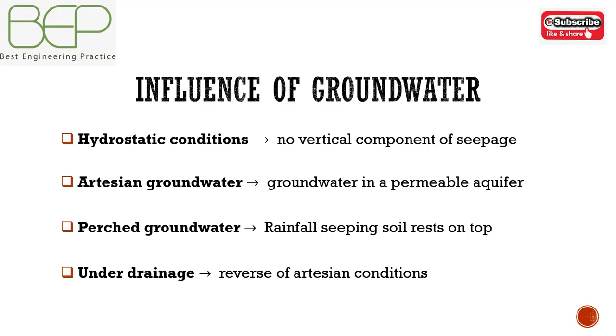The form of groundwater is important not only for the design of the permanent works, it has very serious implications for construction costs because of its influence on the difficulty of carrying out groundwater works. In this respect, it's important to know some details, not only the geometry of the subsoil and the forms of groundwater regime, but also the permeability of each soil type.